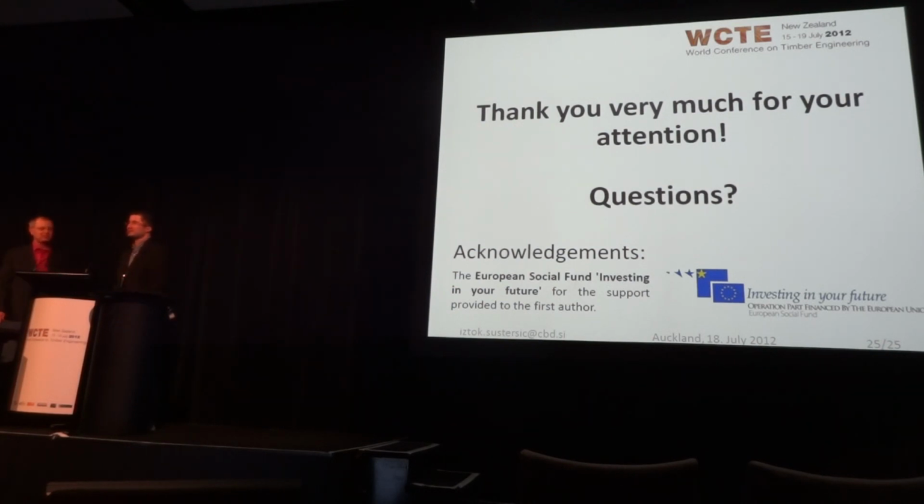I think to keep on the safe side, I would stick to 2.0. I think that's also the value prescribed in the New Zealand code for timber structures. So I'm guessing that they've done some more analysis generally, because we're only dealing here with brackets. It's not that we don't have the nails or anything. We just have to make sure that... So you don't have hold downs? Of course, we can have hold downs, but in our design practice, we often tend to simplify unless we have walls that are very stressed. We just use the same bracket to simplify the design procedure.